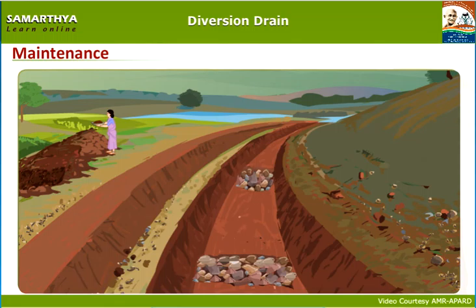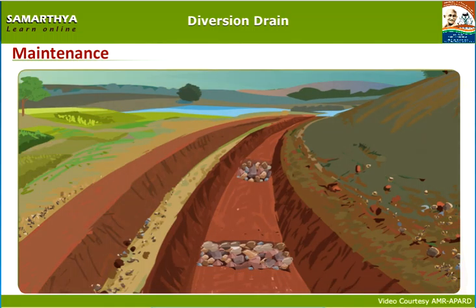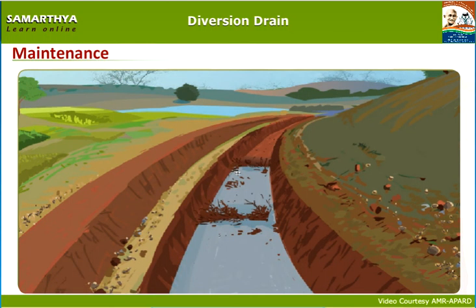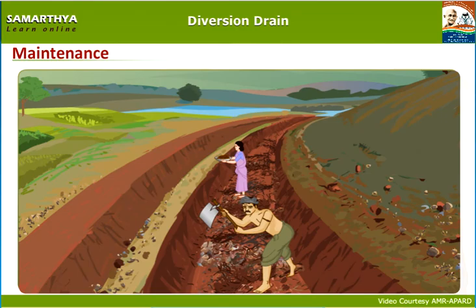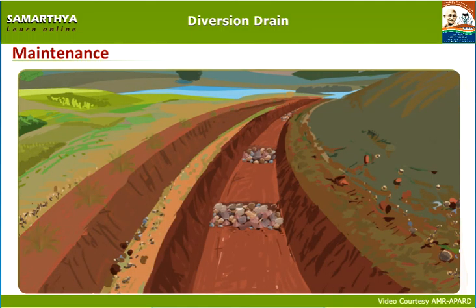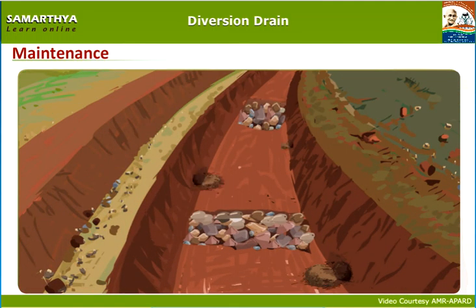Rainwater also brings leaves, debris, rubble and dust, which join the canal and obstruct the flow. So, remove all these as and when filled. Remove any obstacles found in the diversion canal. Grow grass and plants on the bund and maintain them. Rats may dig holes in the slopes of the diversion canal and these have to be filled up with sand.